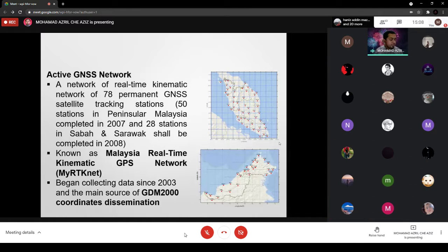you can identify what is the datum. Okay, datum for the coordinate system that will be used in the cadastral, and then you can identify the map projection, and then the coordinate conversion. Okay, and then the coordinate will be used in the cadastral work. So that refers to the Cassini Soldner. You have a Cassini old, and now you have a Cassini geocentric.